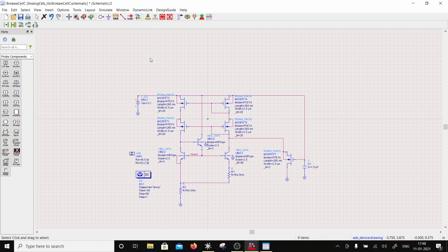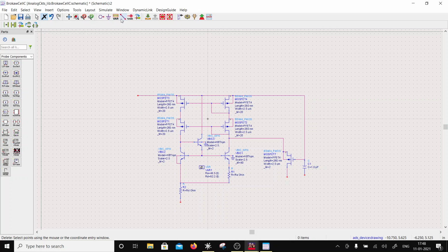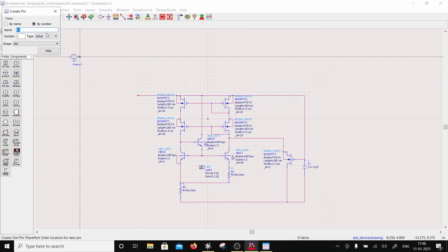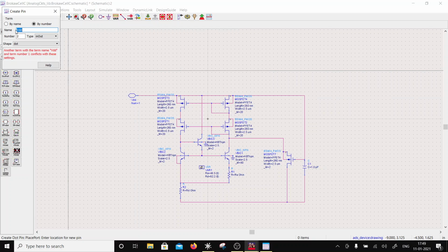And here I'm going to go and throw these components and put in. So this will stay there, and this I'm going to remove. This DC I'm going to remove, and this is my ground, so I'm going to combine all the grounds. Right, so this is the ground. Supply will go away, so this is the 3-volt supply. Right, so I'm going to connect these like this. So this is our startup circuit, and this is VDD, right, and this is ground.